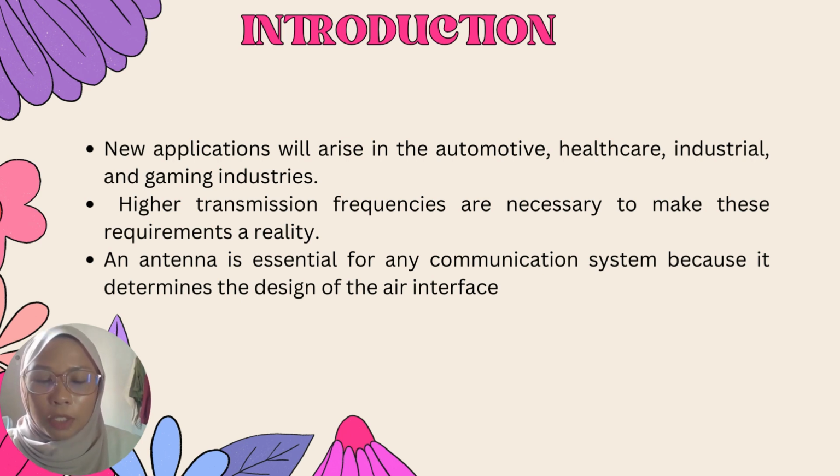Because of the increased propagation losses at these frequencies, larger gain antennas at the base station and mobile terminal will be necessary to enable millimeter wavelength communication. While multi-element antenna arrays may do this, it comes at the expense of increased design complexity, narrower beamwidth, and a more sophisticated feeding circuit. An antenna is essential for a communication system because it determines the design of the air interface.